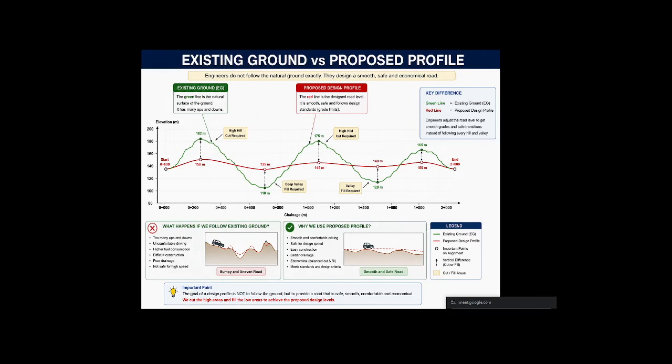Okay. So now we put this into our equation: grade equals vertical difference 10 divided by our horizontal distance 500, multiplied by 100. So we get 2%. So now the road has a 2 percent ascending grade. As well, the grade is a gradient of 1 in 50.